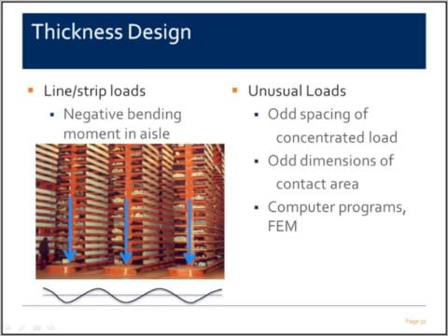If you have unusual loads, then you might want to use a computer program or a finite element method to analyze that type of slab. This concludes my portion of the presentation, and I will now pass it on to Todd.